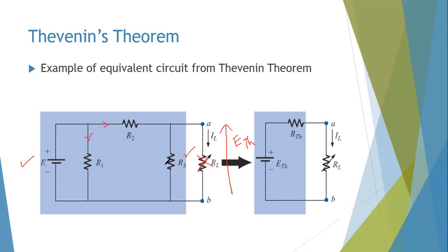These two resistors are actually in series, because the same current is flowing in. No current can flow here. Just don't be confused by that. Some students are confused by that. There can be no current flowing here because it's an open circuit. So if this is capital I, this is now I1 and I2. It splits into two paths. Once I2 flows here, the same current I2 flows through R2 and R3 as well. So this is also I2. And then it goes back, joins I1, and then you have your overall I, which is here.